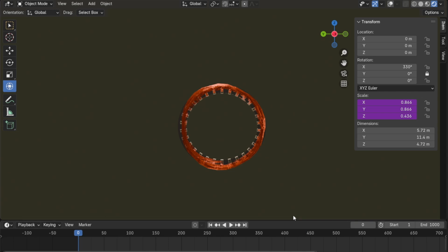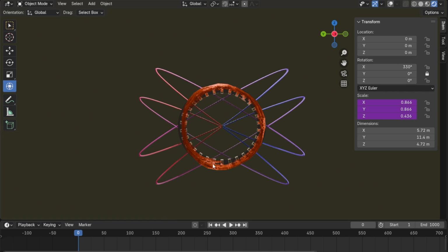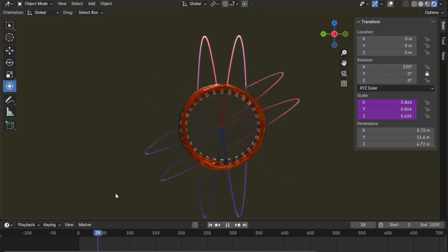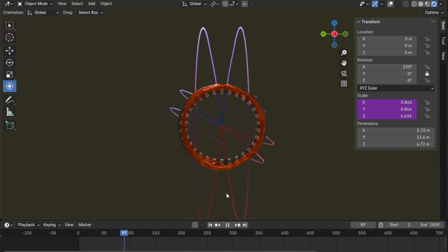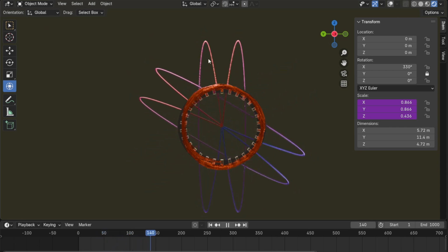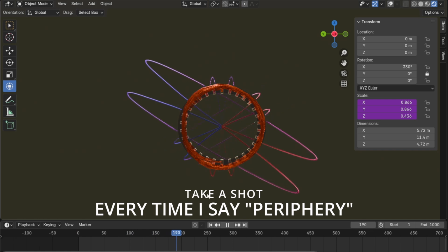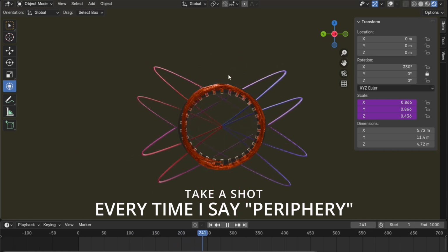So we've got our stator dead on here, and let's talk about these fields now. Since this is a three-phase motor, we've got three individual coils that each have their own dedicated magnetic field, and they're 120 degrees offset, just like the coils are 120 degrees apart around the stator. That ends up creating this rotating magnetic field. You can see the North Pole is traveling along the periphery of the stator, and it's rotating.